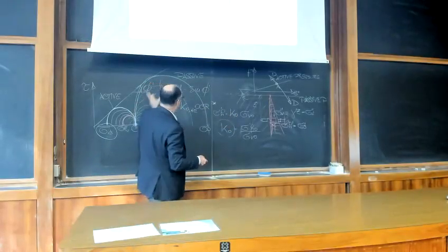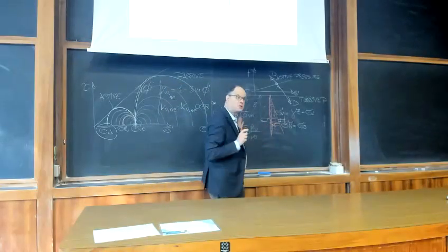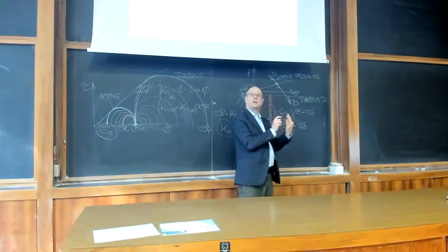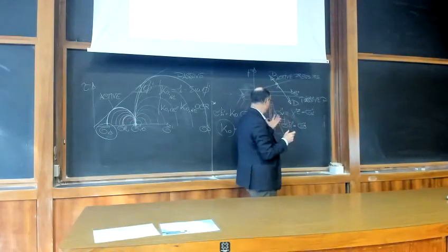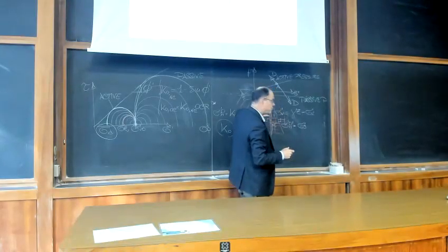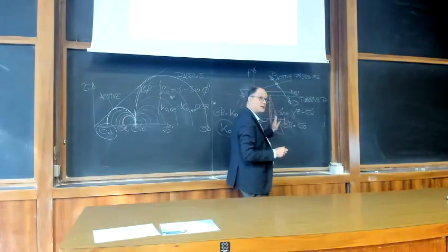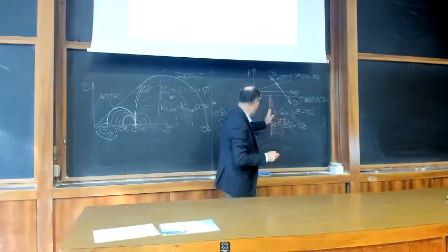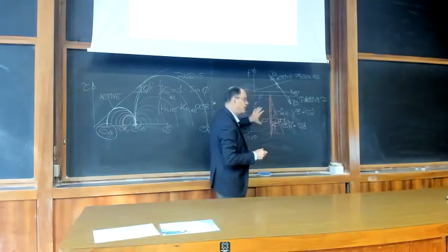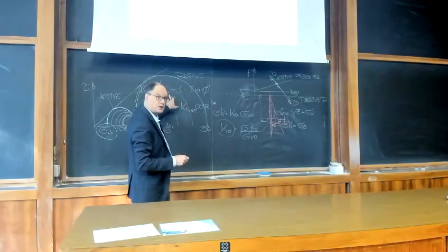Because in order to get to this circle, you have to push against the soil. You have to increase the horizontal stress, compressing the soil. And this is not a possible mechanism. If you remove this soil, the worst it can go is this stays where it is. So the maximum possible pressure against this wall is the initial state, the at-rest pressure.